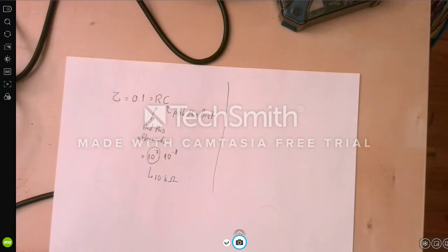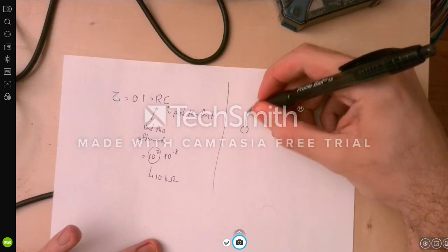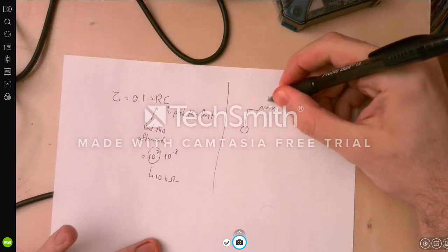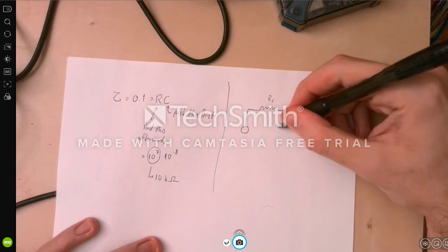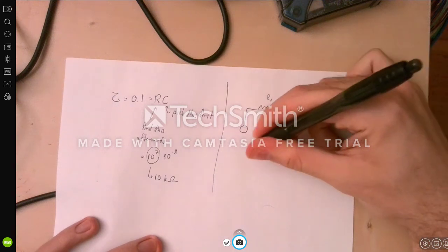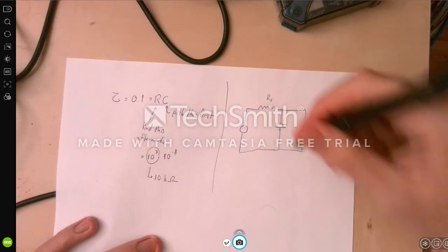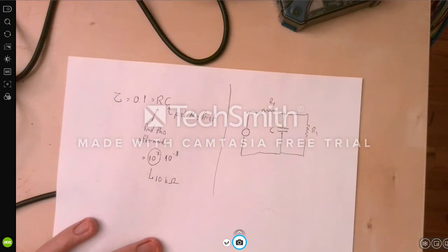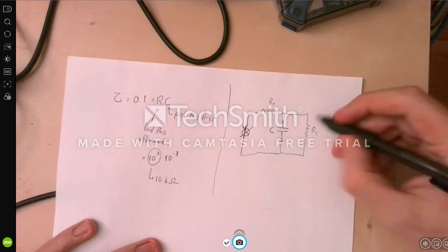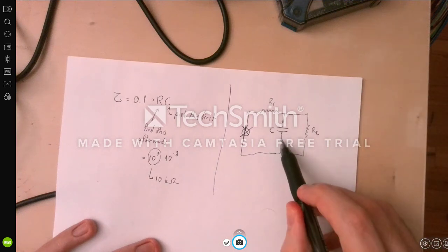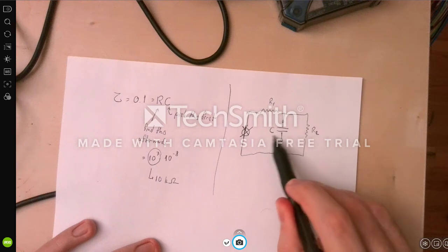If we have this circuit, to find the time constant, we can eliminate all the power sources, which means if it's a voltage source, we can short circuit it, and find the equivalent resistance between the terminals that the capacitor is connected.